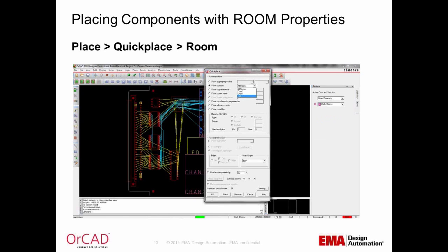Technology files allow you to reuse design parameters, design level constraint data, constraint modes, cross-section information, and user-defined properties. Using the Export Tech File command, you can save off a technology file from a completed board. Then, using the Import Tech File command, that information may be read into new similar board files. So once your chosen technology file has been imported, you can assign the constraint sets from it to the proper nets, net classes, and differential pairs that were imported from the schematic.